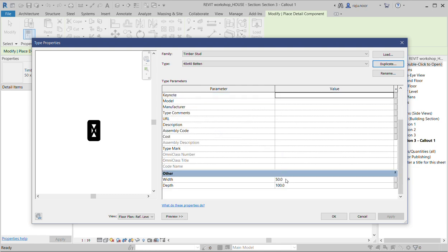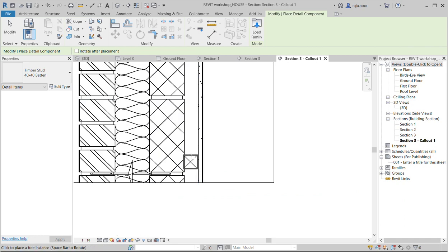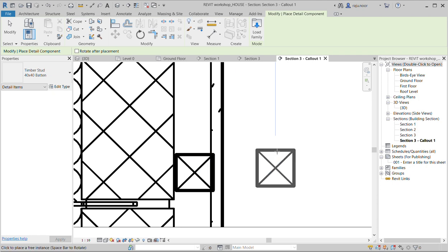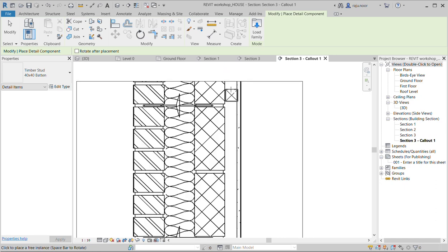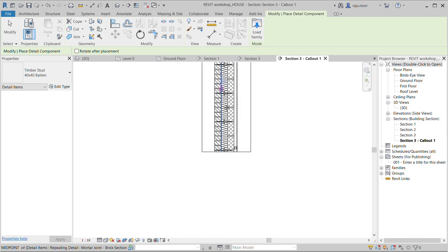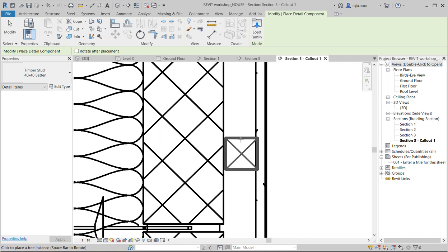Now if you go down, you'll see here this component itself does have editable width and depth factors on them, so parameters on them. So if we go 40 and then make that 42, so that's now a 40 by 40 batten. You click OK. You'll see now it's changed to 40 by 40. Again, I could put them in manually, so I'll just put one in the bottom, maybe at the top. Maybe these again, you can make repeating components out of these.